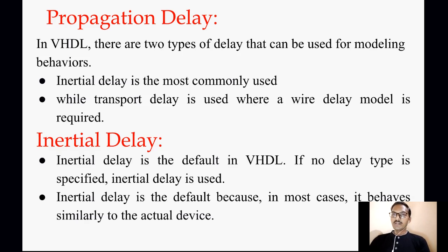Inertial delay is the default in VHDL, and if no delay type is specified, inertial delay is used. Inertial delay is the default because in most cases it behaves similarly to actual devices.